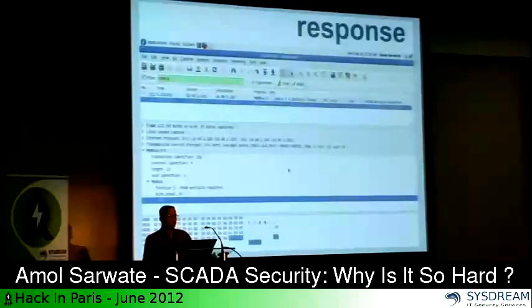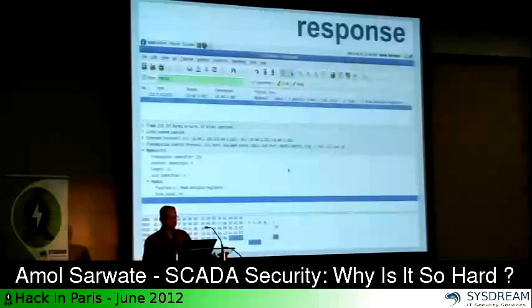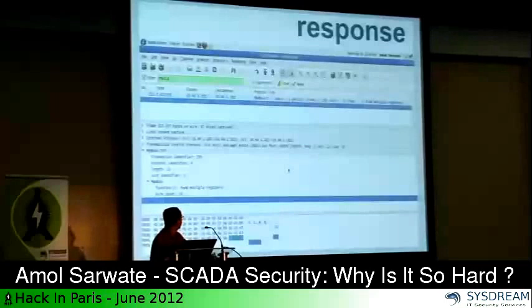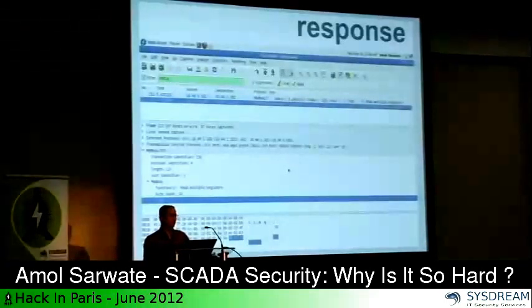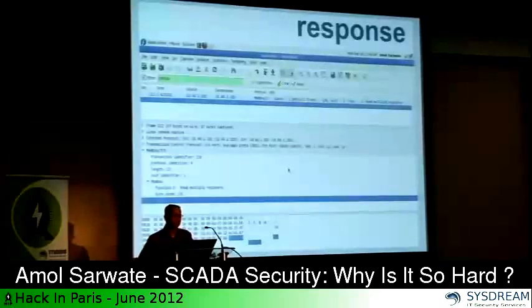The response that we get is something like this. The answer to my question, it gave 10 bytes back of response for 5 registers, 2 bytes per register. So okay, good. I sent a request to some unit. I asked for some values. The unit may be connected to some temperature sensing thing. It gave me back the temperature. So pretty good till now.